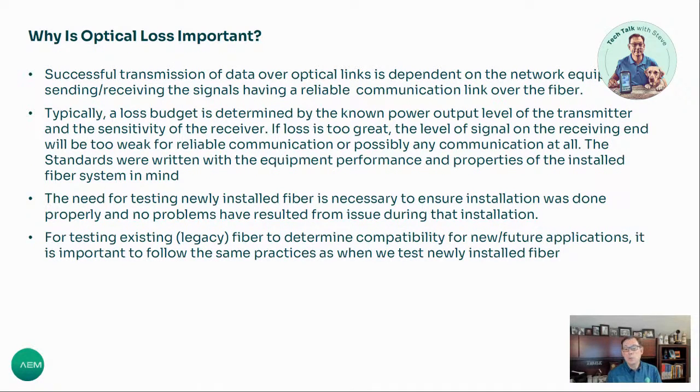Newly installed fiber, or existing fiber if you're going to reuse it, always needs to be tested. You can't just put it in and hope that everything works. It probably will, but you really don't know. So you'd rather test it when you install it rather than wait until you start to hook up equipment and find that you have problems. And typically your scope of work for a project is going to require that you actually test that fiber.